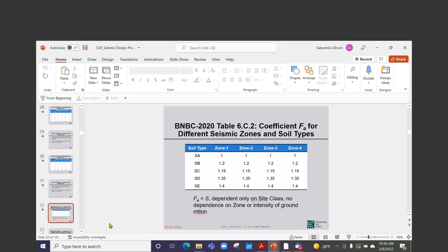And if you want to look at all the historic earthquakes and exclude the entire range where the past earthquakes have been strong, then you won't have much to work with. So my advice would be don't worry about it. Design your building properly according to code, and then if there is resonance, that is fine, the building will still do okay.